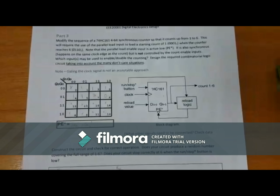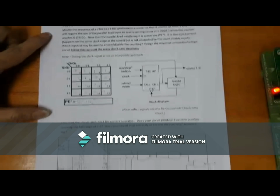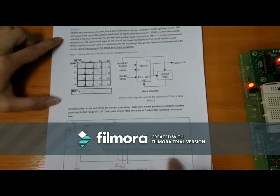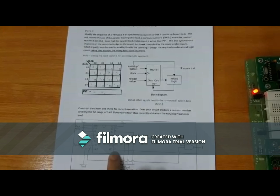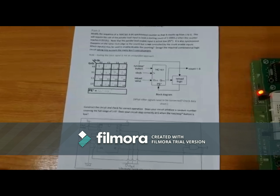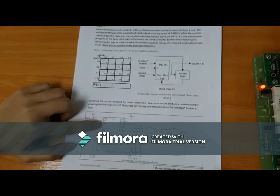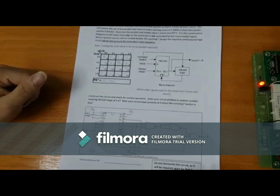And when the count comes to 6, the NAND gate will return 0, so that the PE, which is pin 9, will disable the counting action and cause the data in the data inputs D0 to D1 to be loaded back into its original state, which is the 1 in this case.